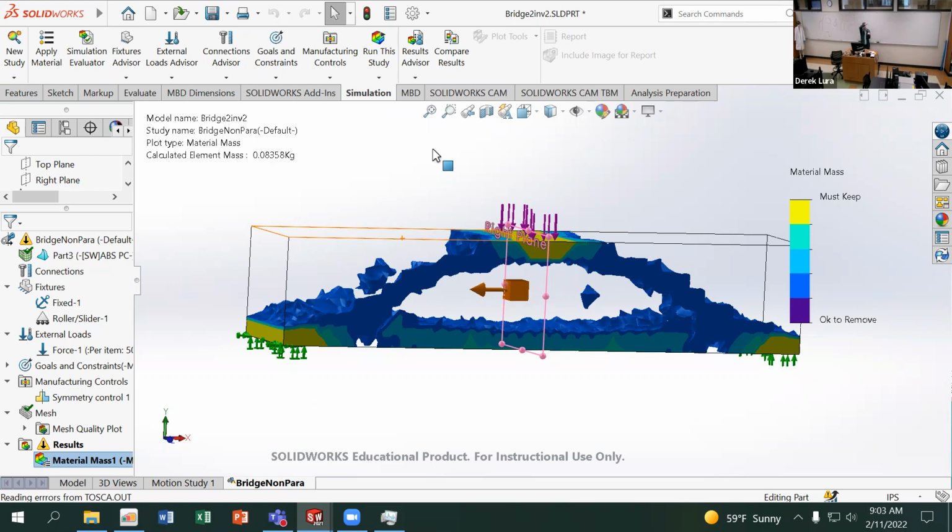But because there's no variance, it doesn't know where to take the material away, right? So since it doesn't know where to take the material away, it just says, I'll just take the material from everything equally and it'll be fine, right? And so that's why you need to have variance and stress and a high resolution, because that'll allow for localization of stress concentration, which will give you results. So hopefully that makes some sense here.